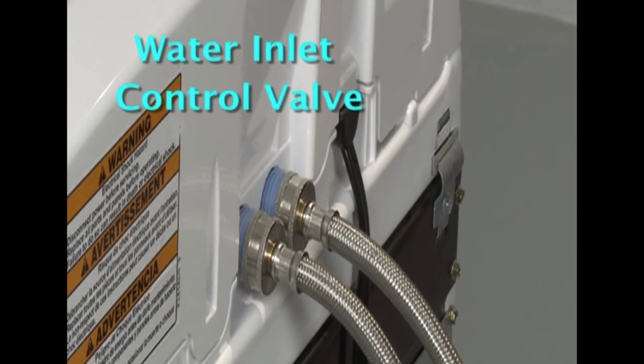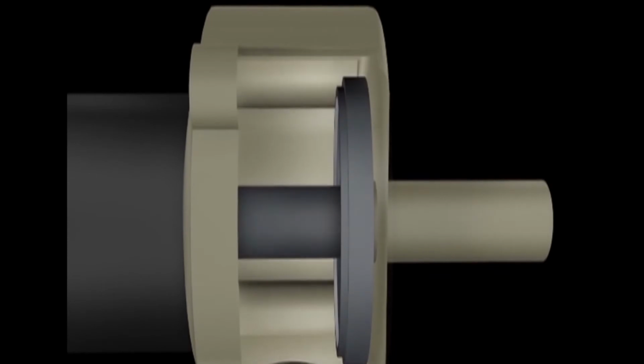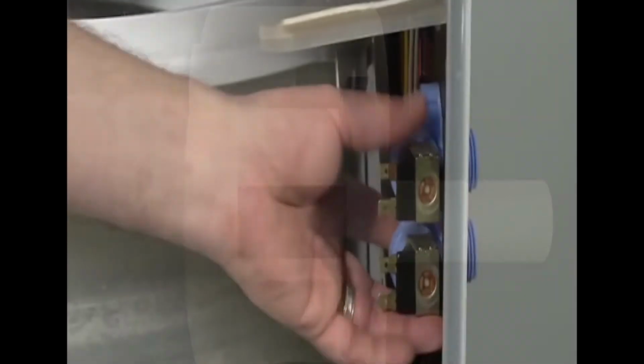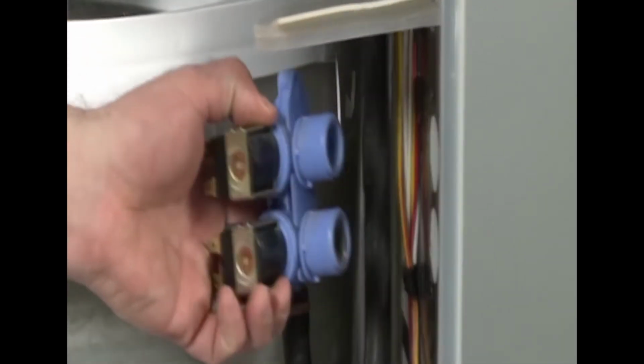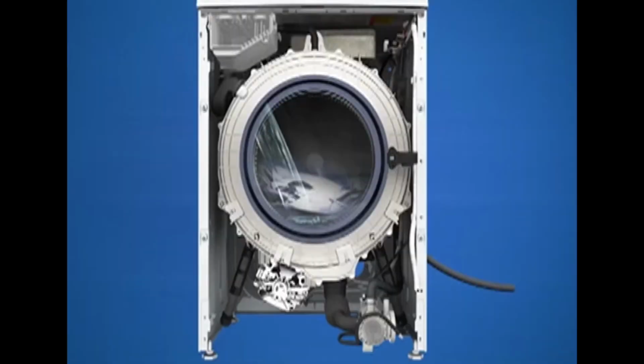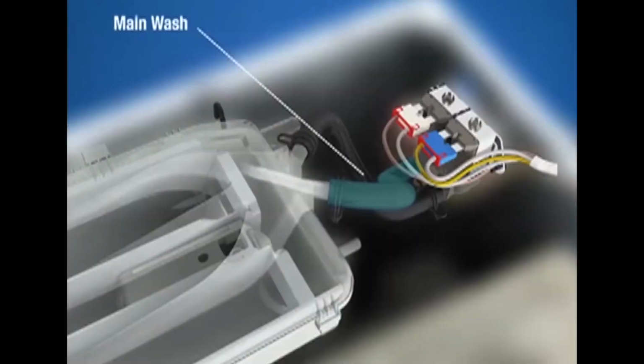What are the parts of the washing machine? Water inlet control valve. Near the water inlet point of the washing machine, there is a water inlet control valve. When you load the clothes in the washing machine, this valve gets opened automatically and closes automatically depending on the total quantity of water required. The next is the water pump. The water pump circulates water through the washing machine. It works in two directions, recirculating the water during the wash cycle and draining the water during the spin cycle.